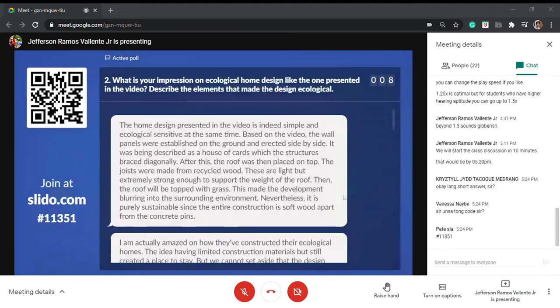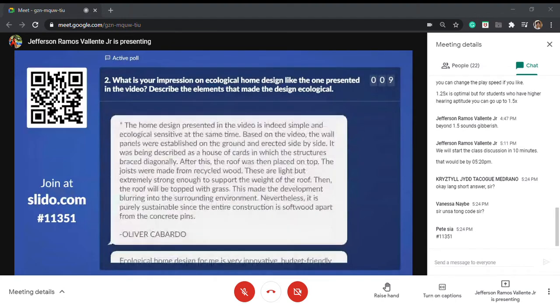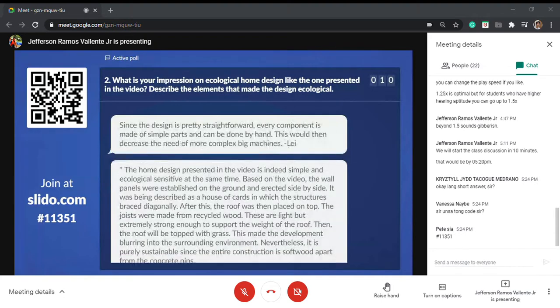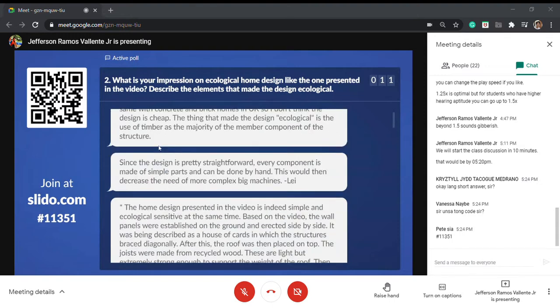There's also the use of a green roofing system, if you notice. But just make sure that when you try to adapt the green roofing system, also consider the weight of the roof. Okay, a green roof absorbs water, and that could be fatal to the structure. Okay, it's heavy as it is. Compared to a GI sheet where water just flows off, a green roof is much heavier. There's also a sharing here that the eco home design, sorry, I always keep pressing it.